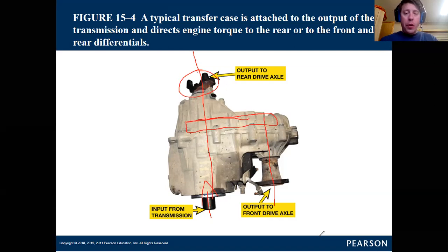They were very heavy, but very rugged. A lot of these older-style transfer cases are desirable among high-horsepower rock crawler and mudding truck guys, because they hold up to the strain and torque much better than a lot of these aluminum case and chain transfer cases.